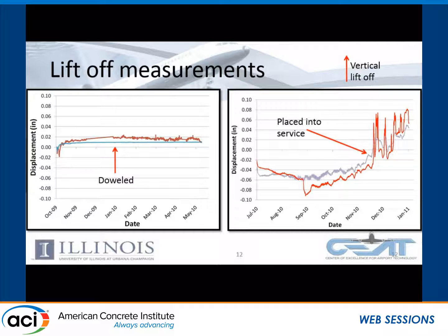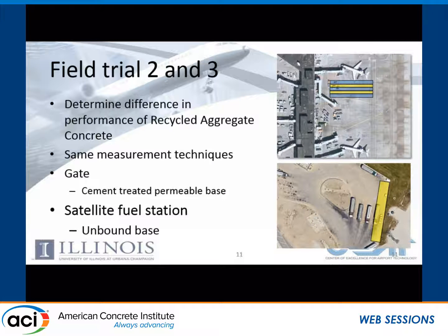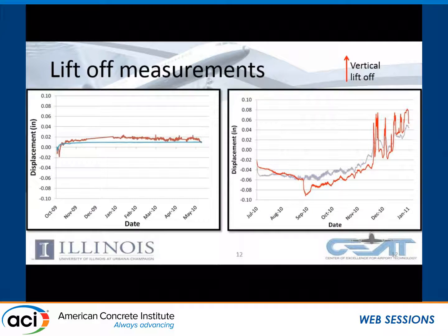So we could actually start measuring the deflections caused by, you can see the fuel trucks that are sitting here. And so those are very, very high loadings. And what happened is with the fuel trucks, they started coming and loading our slabs back and forth, and that kind of dislodged things. And so for the rest of the year, we actually measured a lot higher movement because this is an unrestrained pavement, and then it also has all this extra loading.